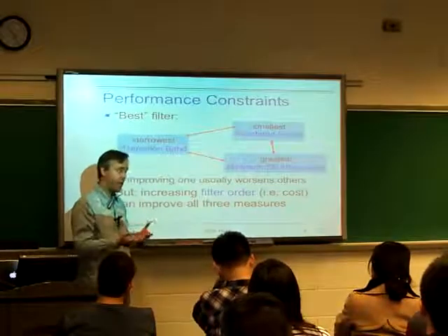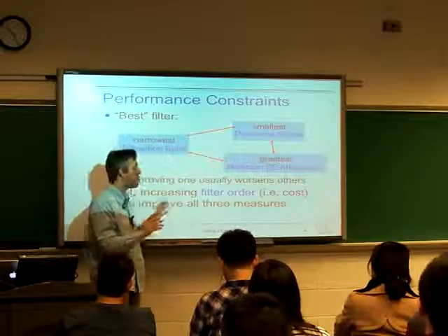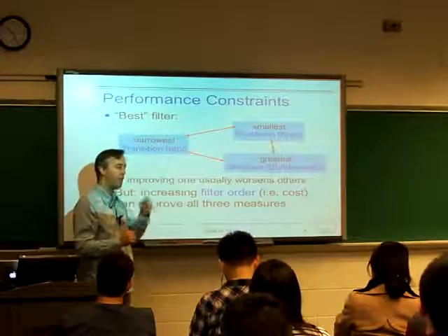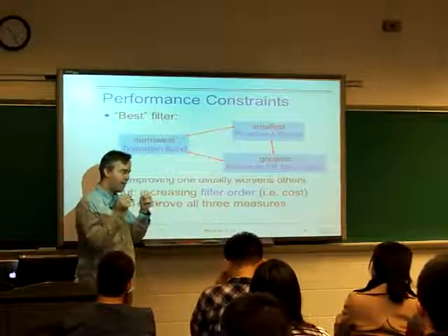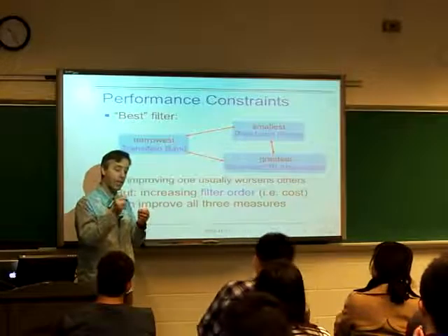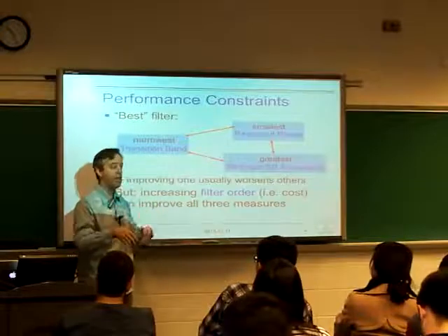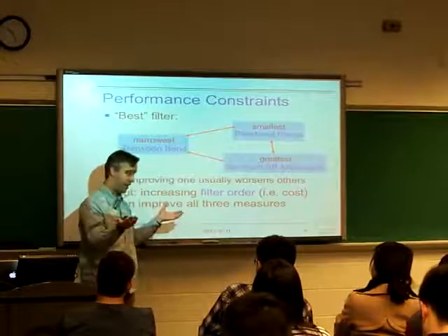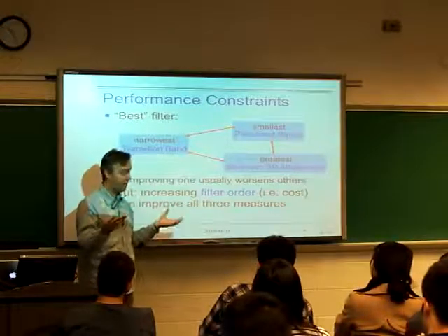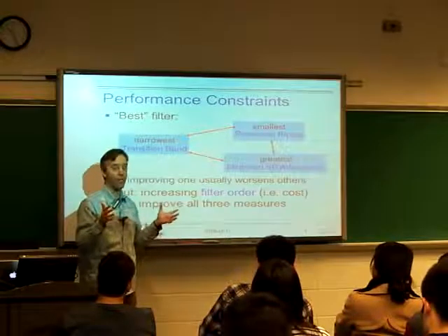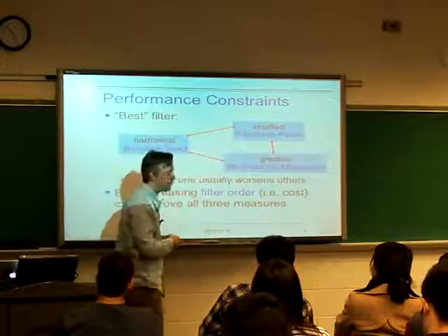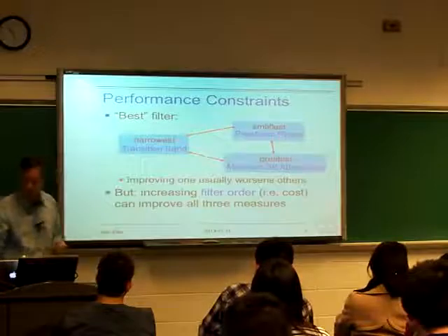But with a real digital system, we also have quantization, which we almost never talk about in this class. But as you get to very, very sensitive systems, and the quantization of the actual coefficients, the fact that the coefficients for your polynomial are being held as, whatever it is, 32-bit or 64-bit numbers, eventually that becomes significant and will hurt.